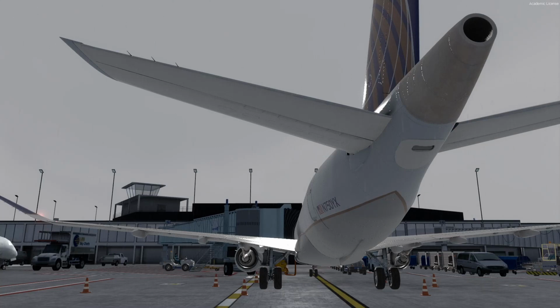For that given, we get a lower maximum takeoff weight. It would be harder to meet minimum altitudes and climb gradient requirements, and therefore potentially lowering max takeoff weight even further. So maybe the runway is enough, but right after the end of the runway there's a big crane which requires a higher climb gradient immediately after takeoff. That's called the second segment climb. So maybe we'll take a hit on that as well.